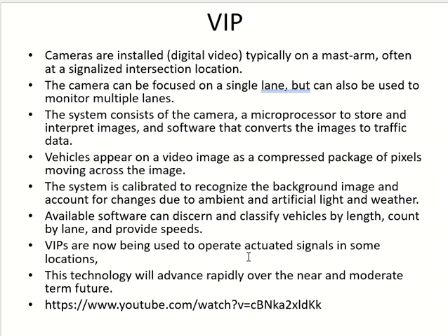The advantage of this system is that you can capture multiple lanes at a time without increasing the number of cameras. One camera can see 3 lanes, 4 lanes, 5 lanes. The challenge is, first of all, to find the location where the camera can see all the lanes without any distraction, even with moving vehicles. Even if it's a big truck, it should not block the view of the camera.